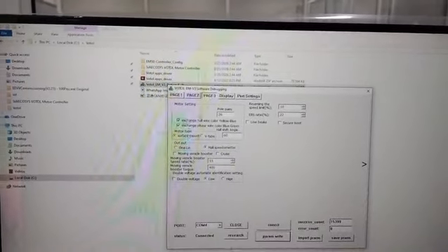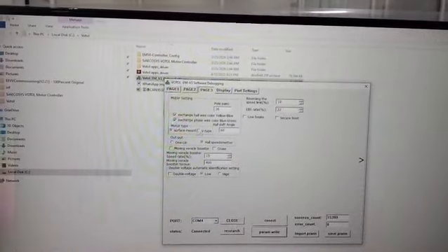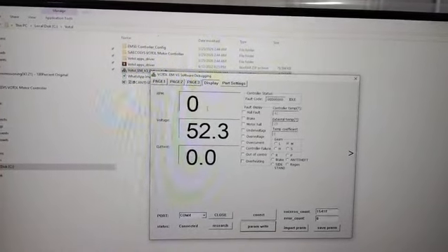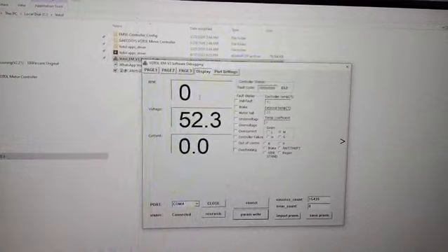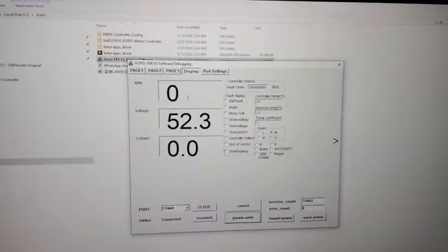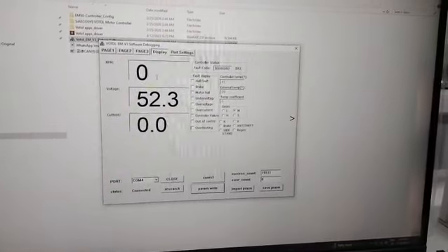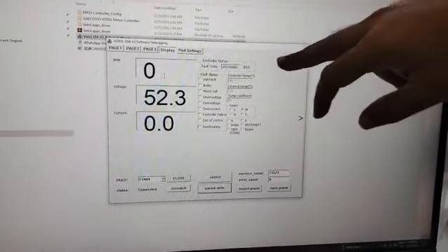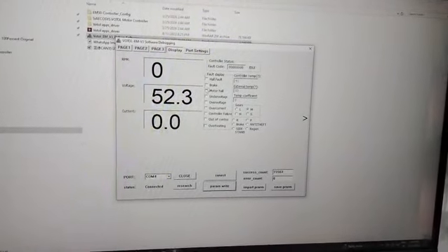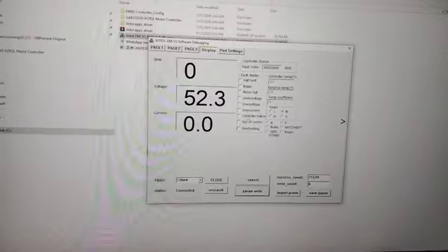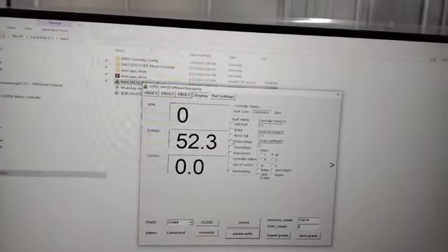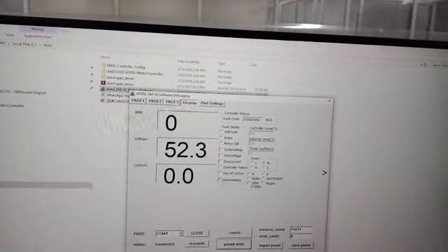In page 3 here is some mounting of this motor we have to operate, and here is a display. Also in this software we capture the faults like brake fault, hall fault or hall sensor fault, motor fault, over voltage and under voltage fault, which are tick marked, so whichever fault we have we will get.